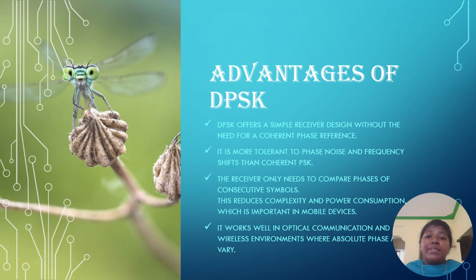Next slide. Now we see the advantages of DPSK. DPSK offers a simple receiver without the need for a coherent phase reference. It delivers the output, and it is more tolerant of phase noise and frequency shift than coherent PSK. The receiver only needs to compare the consecutive symbols, and the lower complexity and power consumption is more important in mobile devices. It works in optical communication and wireless environments. An example of optical communication is fiber, and of a wireless environment is Bluetooth.